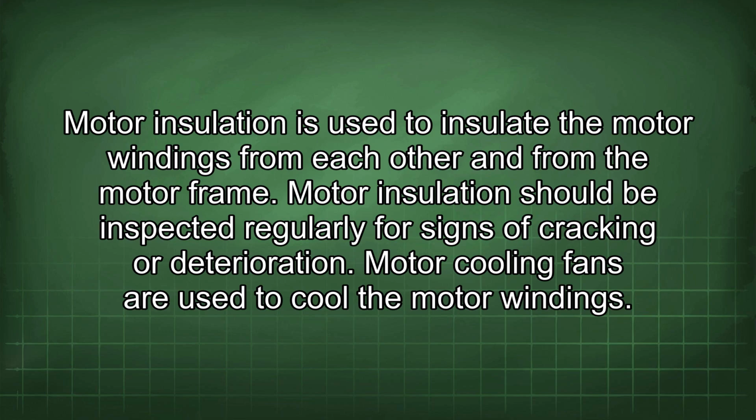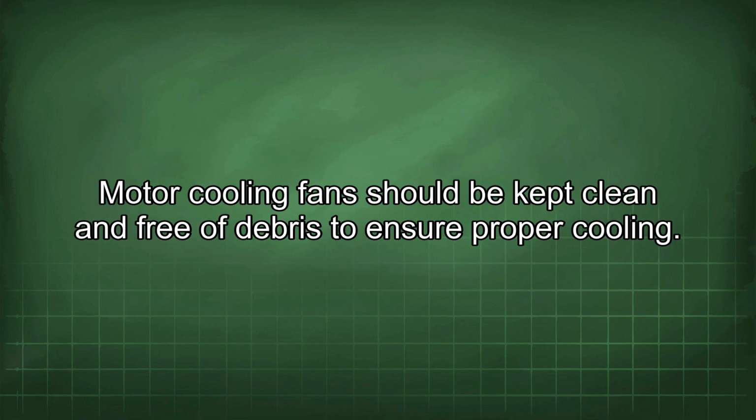Motor insulation is used to insulate the motor windings from each other and from the motor frame. Motor insulation should be inspected regularly for signs of cracking or deterioration. Motor cooling fans are used to cool the motor windings. Motor cooling fans should be kept clean and free of debris to ensure proper cooling.